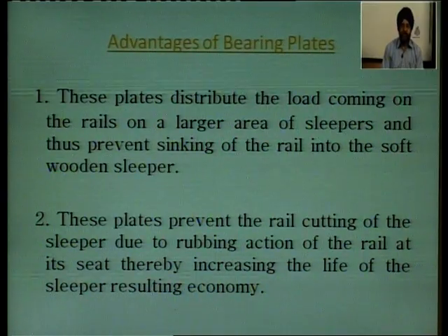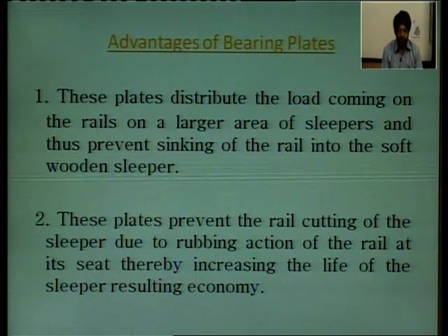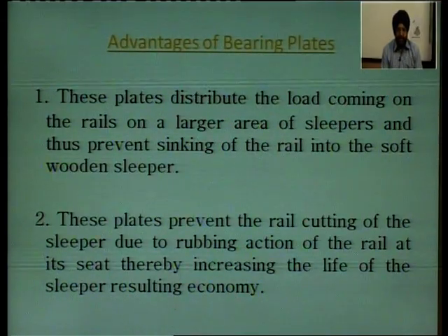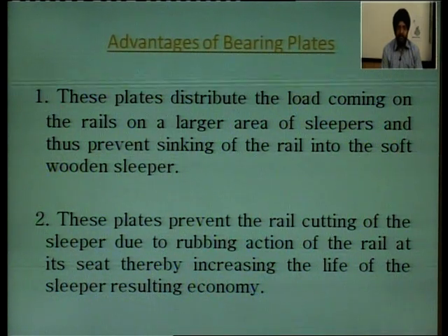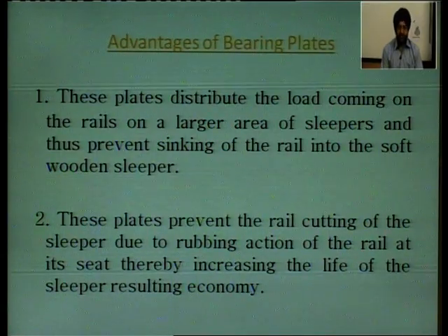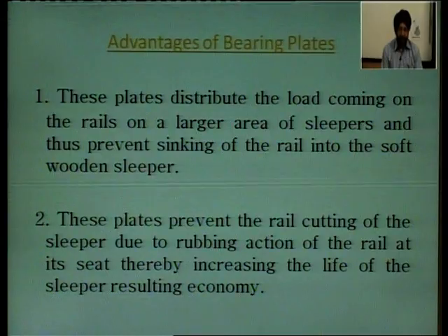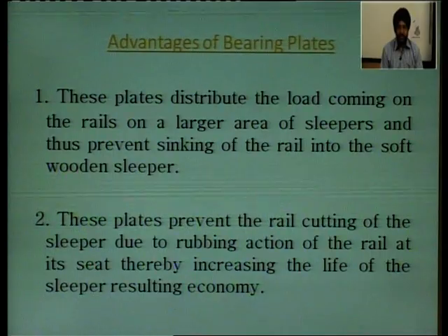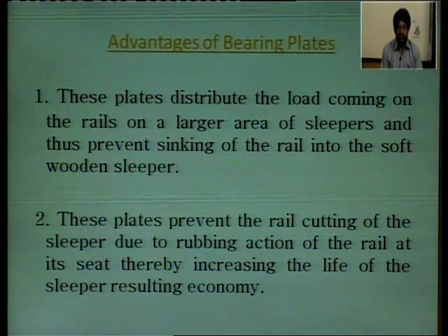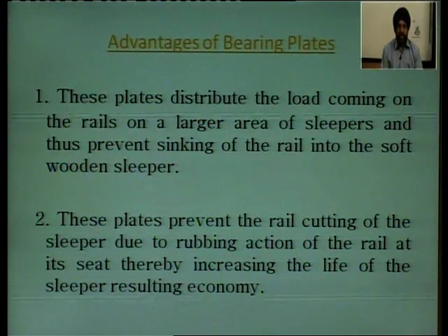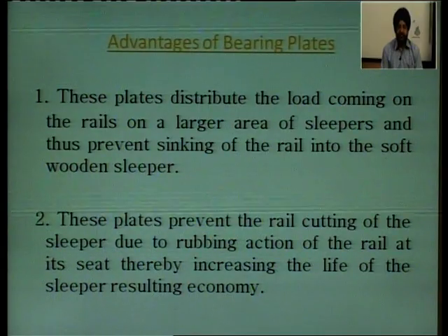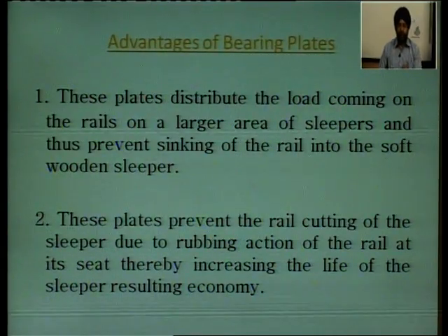Now, the question is, what are the advantages of using these bearing plates? Yes, there are many advantages. Firstly, these plates distribute the load coming on the rails over a larger area of the slippers. The rails have a narrow section, while the slippers have a wider or broader section. So, by transferring the load on the rails to a larger area of the slippers, they prevent the sinking of the rail into the soft wooden slipper.